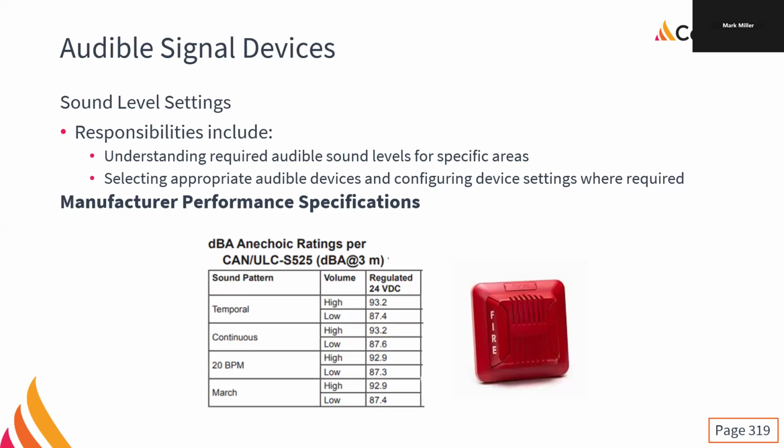Typically, what we use for the first stage is something like 20 beats per minute. So it's very slow in comparison. It's got kind of a chill sound to it. It's like, hey guys, stuff's going on. Pay attention to what's going on. If you see a fire, run away, all that stuff. But it's not "evacuate the building." So it's annoying, but it's not really designed to make you feel the absolute need to exit the building.